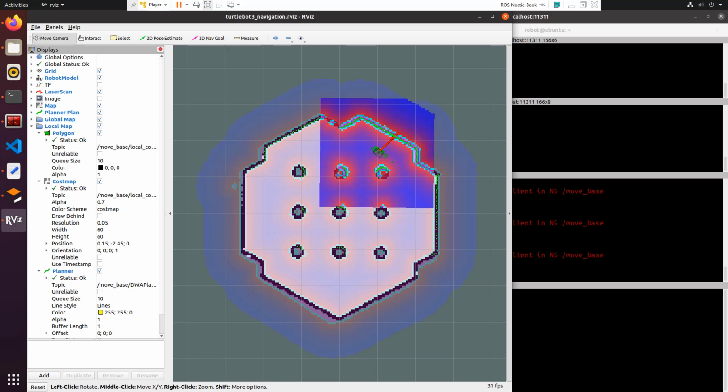Only then can we give the next request. But ActionLib is not like that. I mentioned that the ROS navigation stack is actually an ActionLib server, or action server, so that we can give the request. What we are seeing is that we are using RViz and giving a request, right? So here RViz is acting as an action client.